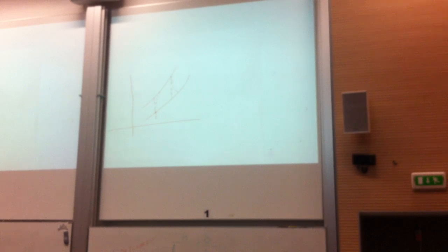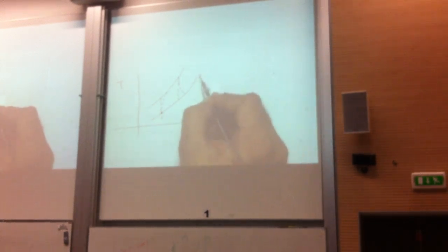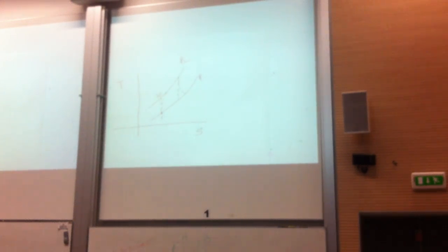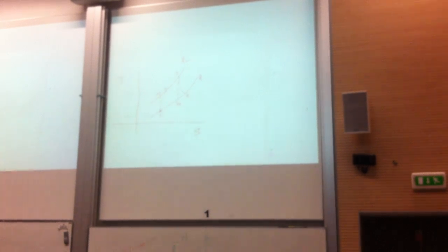Plotted that, it used to be ES, now it is TS. So this is our state 1. This is P1. This is P2. These are the different isobars. On these lines, pressure is constant. From 1, you can go to 2S, straight up, meaning constant entropy. From 3, at higher pressure, you can come up to 4S. You can come up to 4.